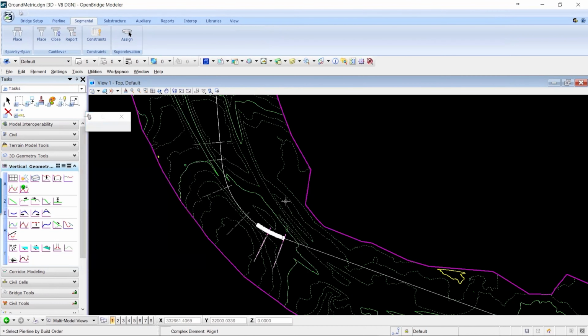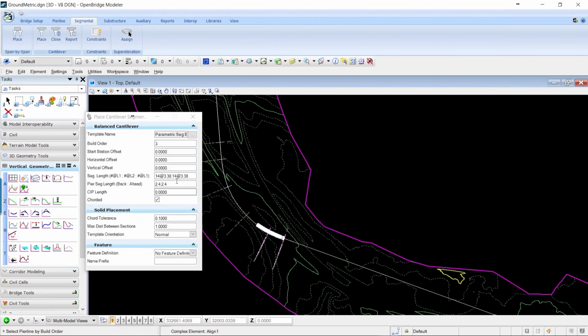Coded means precast segment. In a precast segment, in the casting cell, you know that the sides of the segment are perpendicular to the face of the segment. So it's not exactly perpendicular to the curved alignment. The sides of the segment are straight and not curved. That's why we have a slightly different geometry, but which is very important when we create a report. So we do it like span by span, okay?